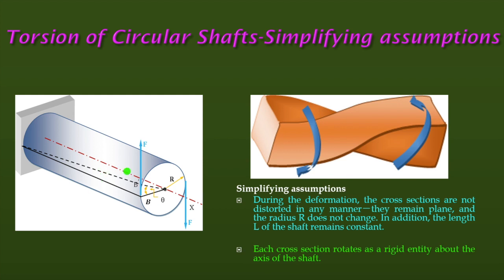An angular twist like this. Though here it is a rectangular cross-sectional object, in this example it is a circular shaft. To represent the twist, it is better to give an example of the rectangular cross section. That's why I have shown here the rectangular cross-sectional area twisting. A similar phenomenon we will observe in the case of the circular shaft.